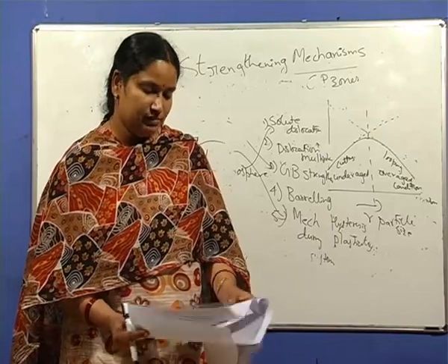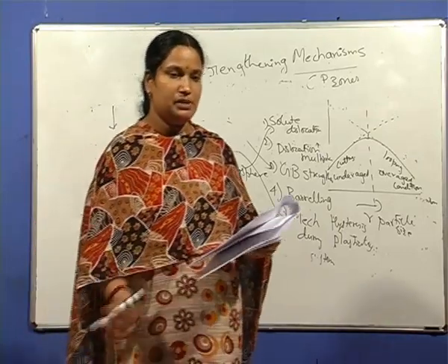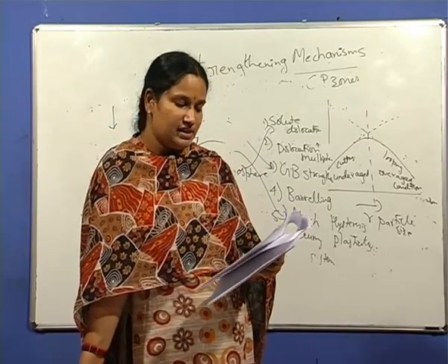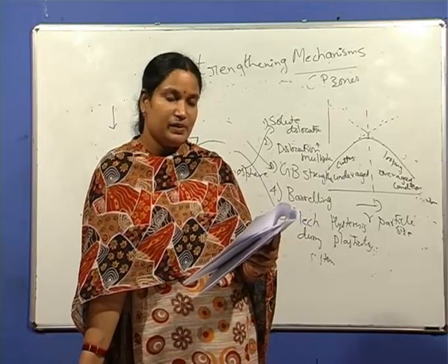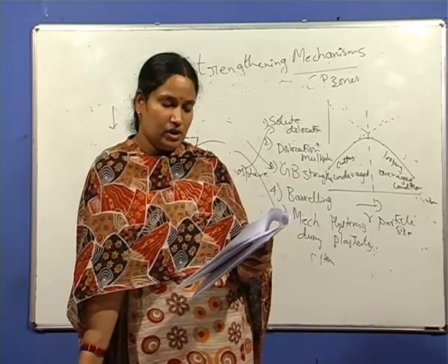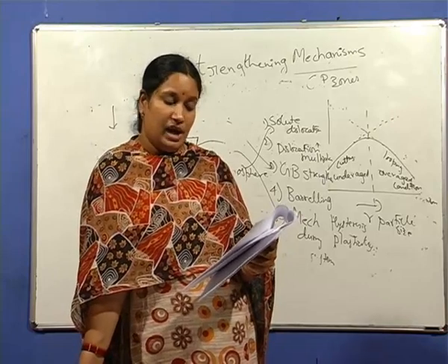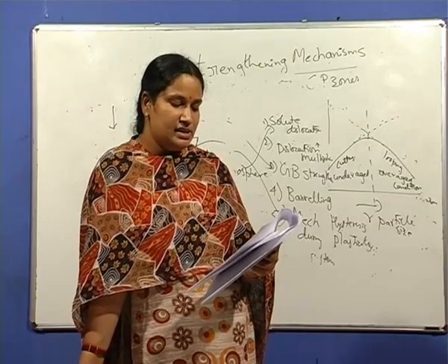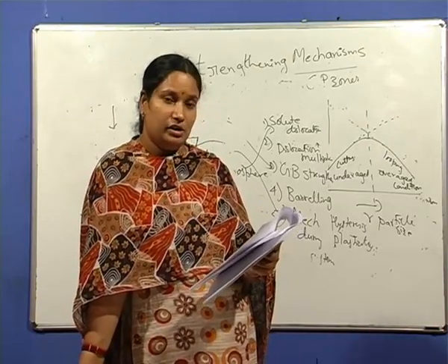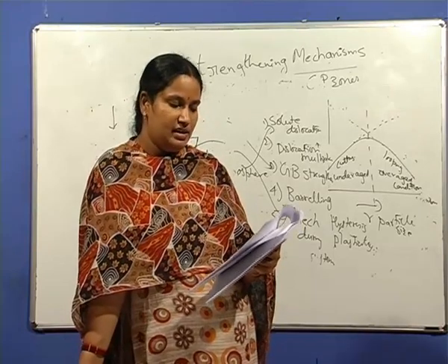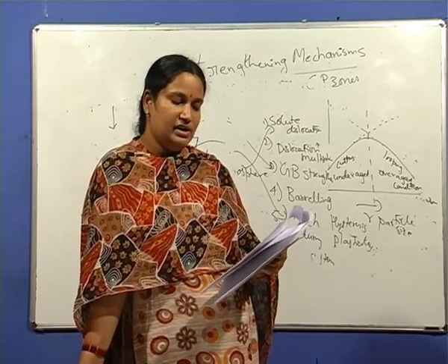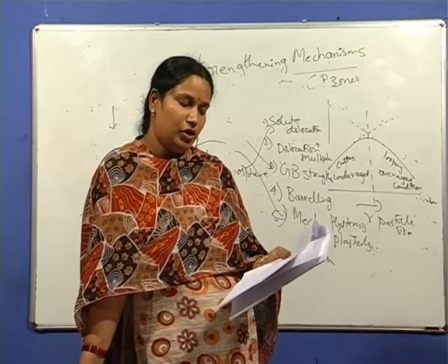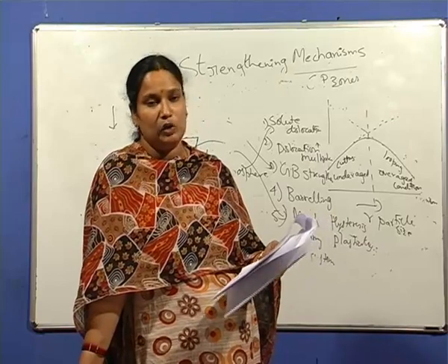And one more question, that is question number 34. Stacking fault energy plays an important role in determining the work hardening ability of a metal. In this context, the correct logical sequence is: A, high stacking fault energy, easy cross slip, low work hardening. Second option is high stacking fault energy, difficult to cross slip and high work hardening. Third option is low stacking fault energy, easy to cross slip, low work hardening. And option D is low stacking fault energy, difficult to cross slip and low work hardening.